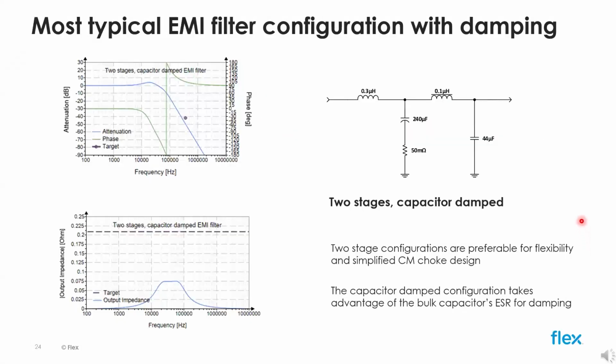The discussion about filter output impedance is obviously applicable to the differential mode portion of the EMI filter. The multi-stage filter in this schematic is a good example of a typical application. If we recall our discussion about filter equivalent circuits, this filter configuration may result from a large common mode choke connected on the output side of the filter, so that the small output inductance in reality is a leakage inductance. Similarly, the RC network can simply represent a large electrolytic capacitor with its own equivalent series resistance.